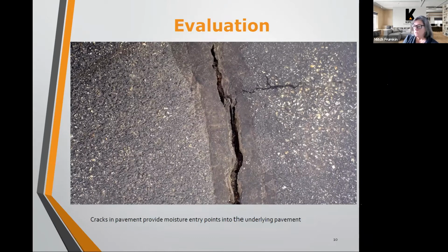So it becomes the maintenance cost, and the continual maintenance becomes a losing battle after a while. And one of the most damaging things about the crack is not the crack itself, it's the fact that there's water getting in there and it's doing damage underneath the pavement. One of the things I want to point out as important is that the damage that can be done by water entering pavement is progressive.